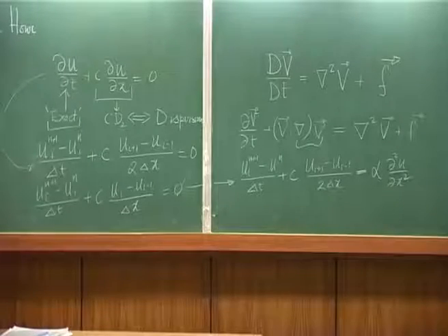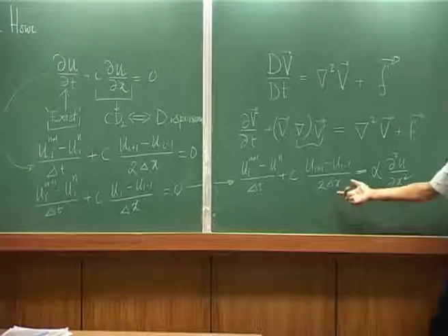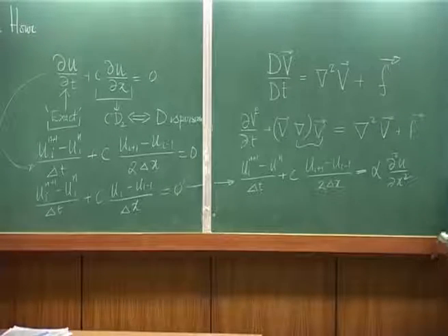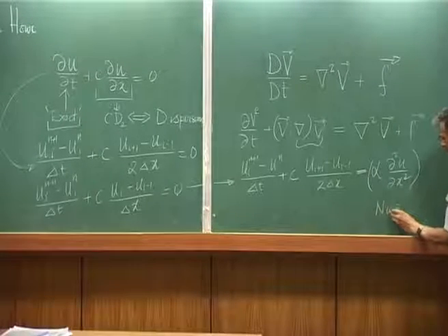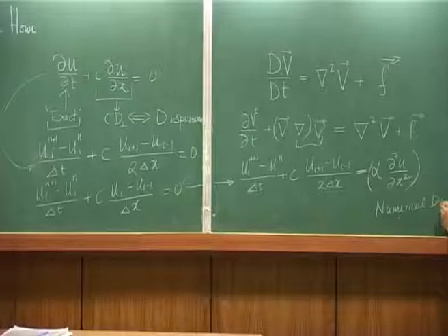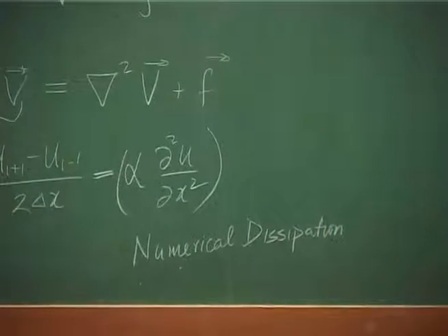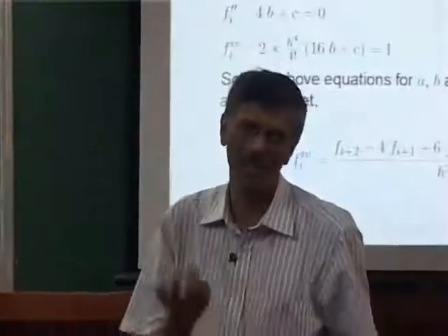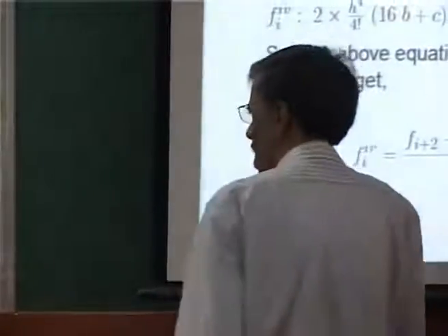So, what we are essentially saying is, look at this, first order upwinding is equivalent to doing a second order stencil plus adding a numerical dissipation term. So, this is not there. This is what I will call numerical dissipation, right. In fact, most of computing activities relate to suitably designing numerical dissipation to do your job. That is what we would see as we go along.